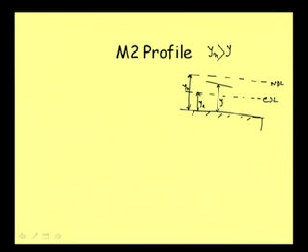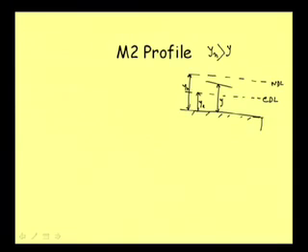that means this, because the profile will always be between Yn and Yc. So, y is bound to be less than Yn, but it is again greater than this y, depth y is always greater than Yc, because the lowest limit of the M2 profile is, or rather we can say the lowest limit of the zone 2 itself is the critical depth line. Well, so Yn is greater than y, and this is greater than critical depth Yc.